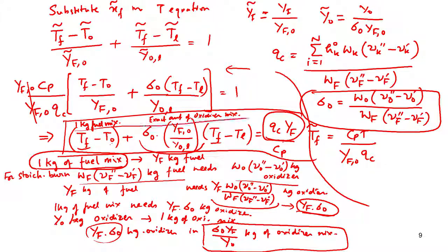So, this is one very important thing about a non-premix flame, that the temperature reached is always the adiabatic flame temperature, and you can clearly find it from this equation, that is why the flame temperature reached is the adiabatic flame temperature. But I suggest you go through the book also, and go through this derivation once again to convince yourself that this is the case, alright.